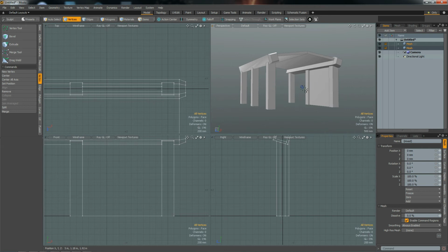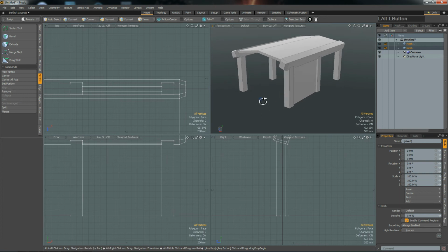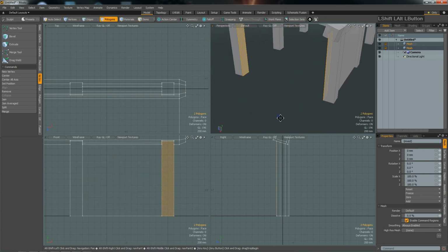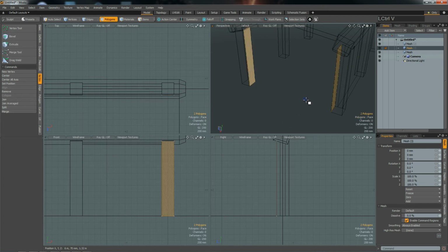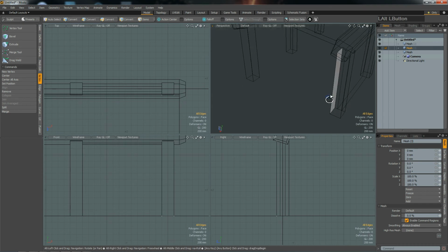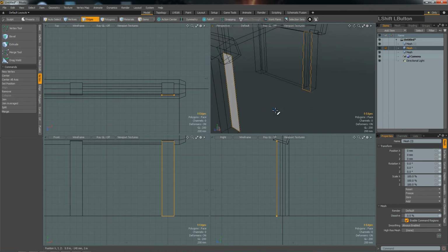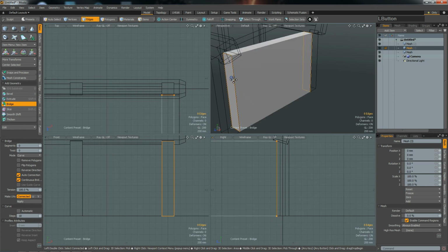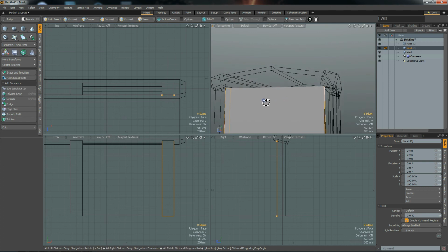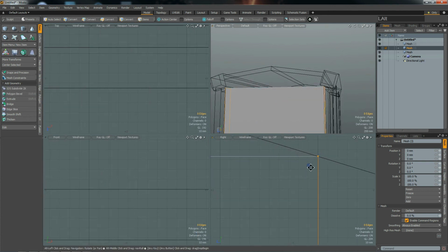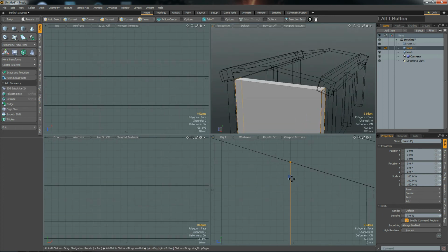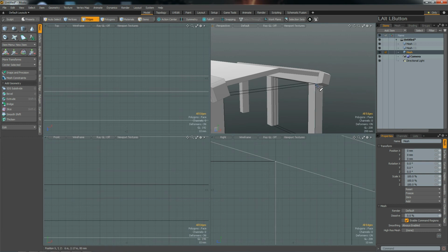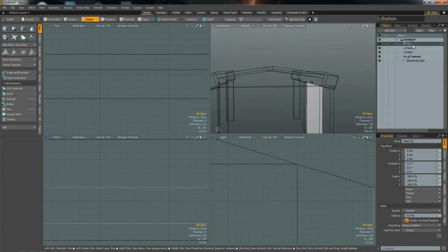Now we create the front part, and we do this basically the same way, although here I start with my two polygons that I have here. Control C, new mesh layer, Control V, F key to flip. I select the polygons, I hit the bridge key, I deselect remove polygons, I'm going to bridge them now, they stay. So just to illustrate that. Since we copied from our wall inside faces from these, the height of this one is perfect, as it should be.